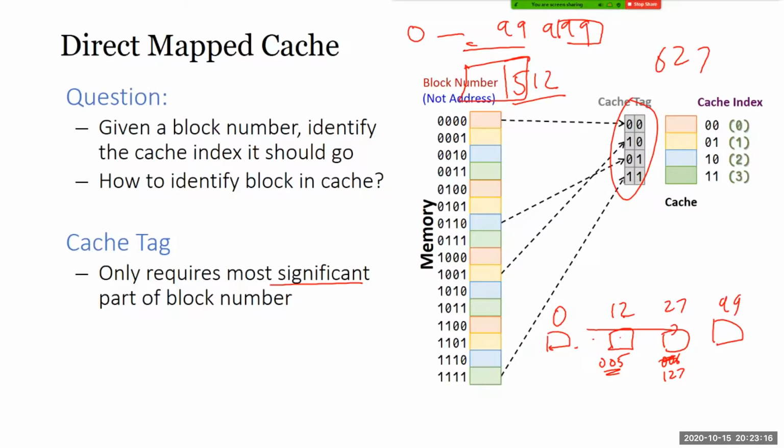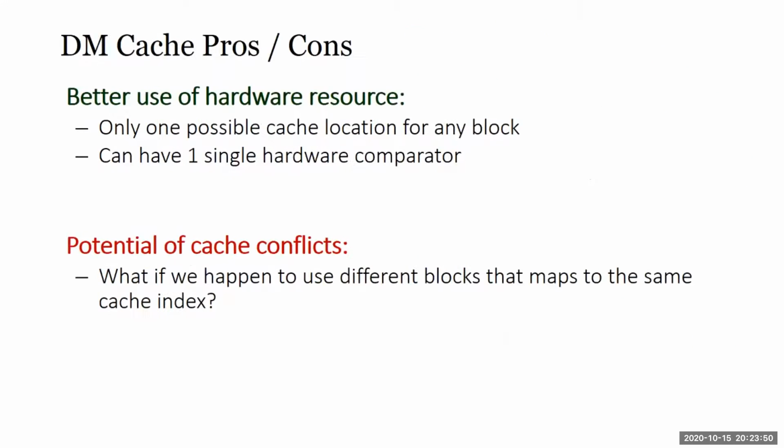So I will have to go to main memory and fetch the book. This way, yes, it is not so flexible, but it makes the retrieval mechanism more simplified and not expensive. Remember, this is all in hardware. They must design wires and transistors inside there. If you have very complicated wiring, and wiring has to jump over everything, then you don't have enough real estate for other stuff. So here we sacrifice a bit of flexibility and have simpler wiring, so we can have a bit more space to maybe make the cache a bit bigger. These are all the trade-offs.